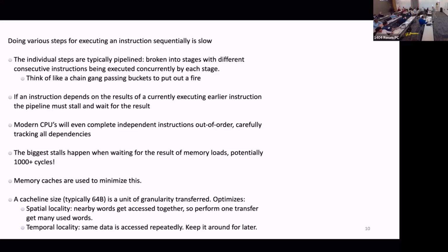The Xeon, the Skylake chip I was looking at, was looking over the first loop, stalling these, and then if you're doing SU3 times SU3, you've got row-column products, right? It was then going to the next row and starting the first instruction of the next row while the first row was still in flight. It unrolled the entire thing and reordered loops, in hardware, and got basically peak. So I thought, oh, this works. I can stop writing my own compiler and rely on these kinds of chips being able to run efficient code. So that's out of order CPUs.